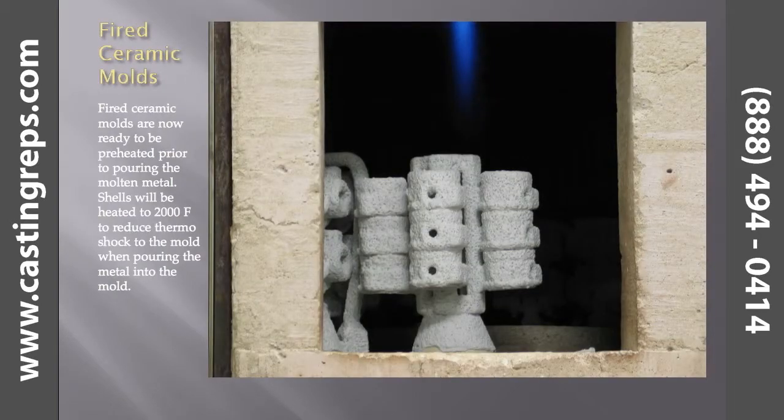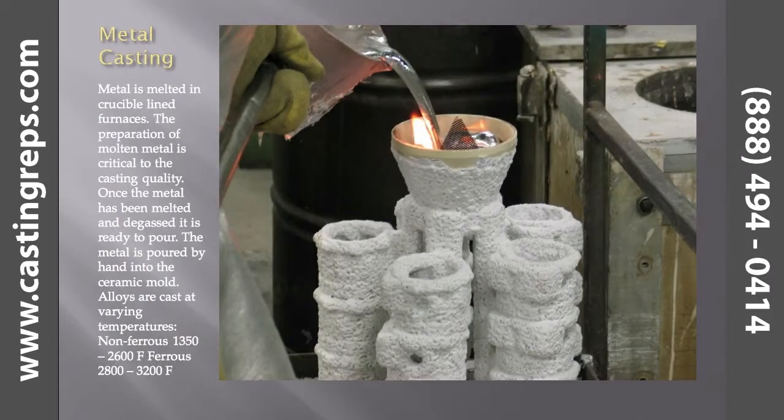Fired ceramic molds. Fired ceramic molds are now ready to be preheated prior to pouring the molten metal. Shells will be heated to 2000 degrees Fahrenheit to reduce thermoshock to the mold when pouring the metal into the mold. Metal casting. Metal is melted in crucible-lined furnaces. The preparation of molten metal is critical to the casting quality. Once the metal has been melted and degassed, it is ready to pour.